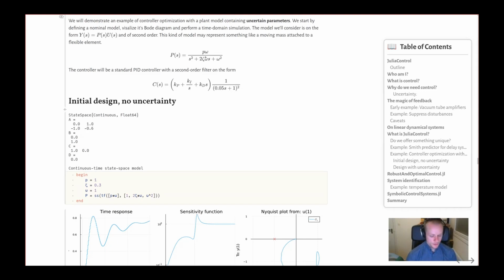So if you move a motor very slowly, it looks like a double integrator. But if you move it very fast, the gearbox actually becomes a bit flexible. And when you reach your destination, you might have some oscillations due to this flexibility. So the gearbox behaves like a spring. So this is actually a reasonable model of such a system.